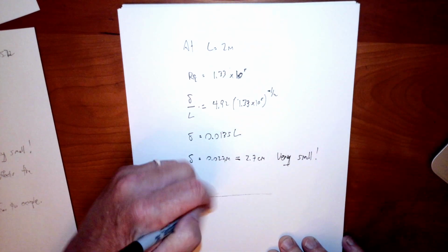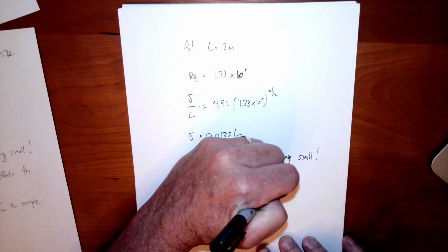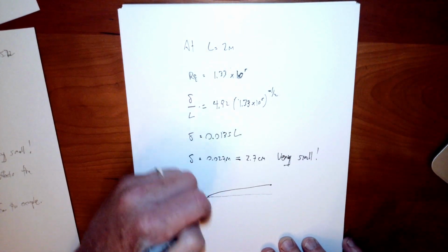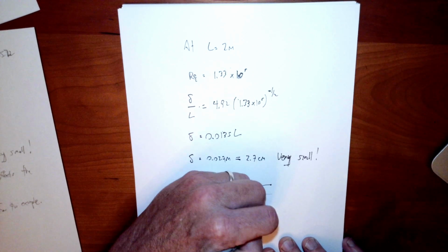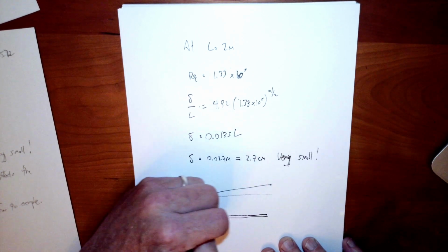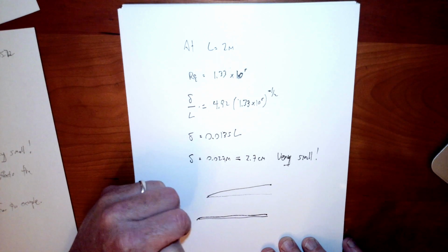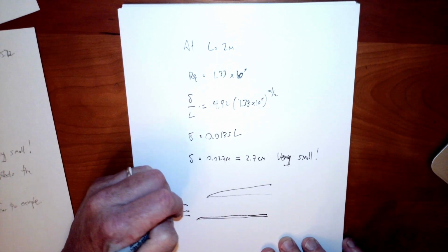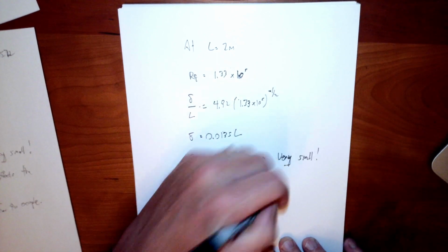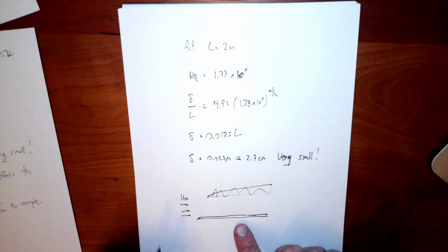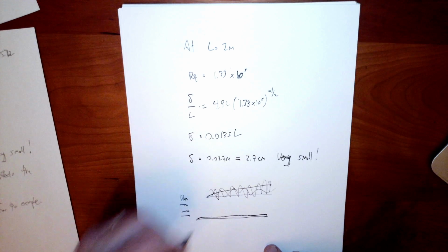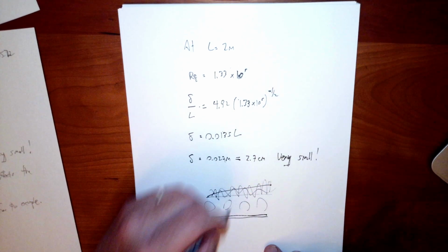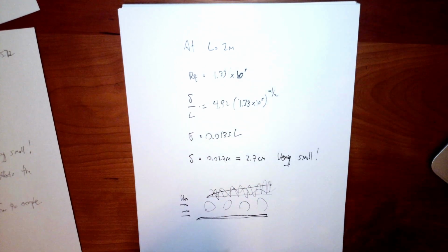If you were to draw the viscous boundary layer for flow over the plate, it's not anything like what it looks like. You'd have to draw it where this is 1/100th of the length of the plate. So it'd be very, very thin. These viscous boundary layers in airflow in particular tend to be very, very thin, which is one of the reasons that you can use the assumption of no viscous effects when you're not near the plate. So things like the Bernoulli equation can be used up in this region where you're not in the viscous region.